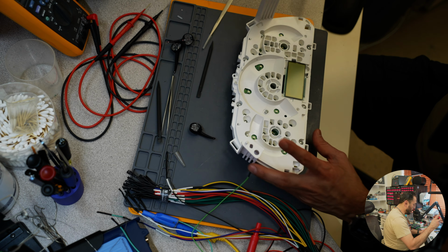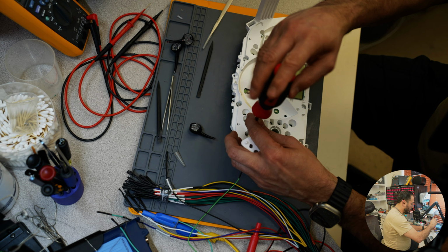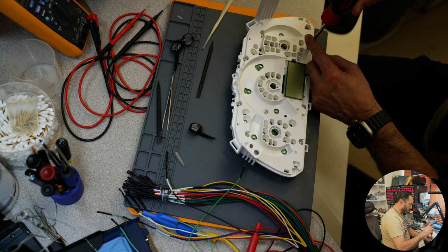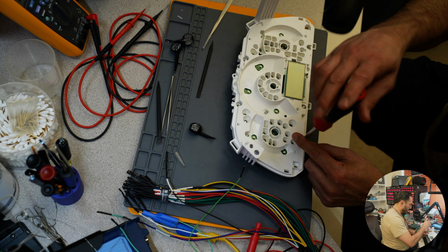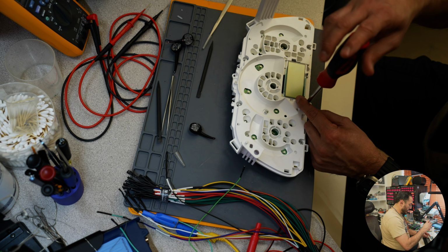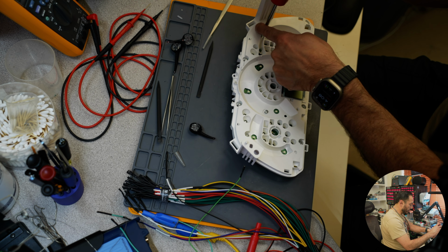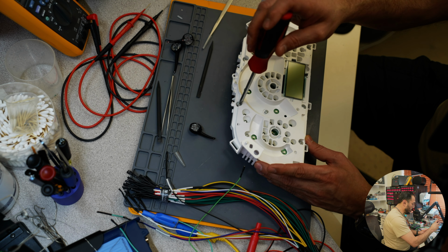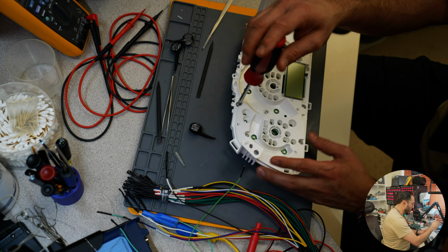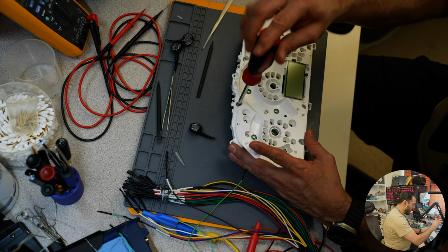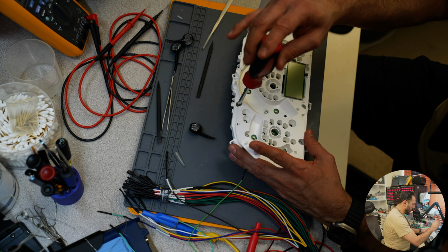Okay, now that we have all the screws in place, I can start at least 4 of them, so we know that we're aligned properly. If you want to start them all, well, then that's not a bad idea either, because then you know that you're not going to force them into place just because you tightened up 2 or 3 first. I always recommend doing that with everything, because then you allow the same part to align itself. Right now they're all in just by hand.